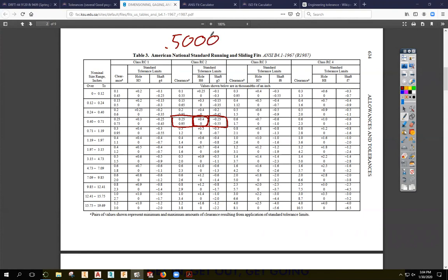So my hole size is 1/2 inch, right? My tolerance is going to be plus 0.0004 minus 0. That's 0.4 thousandths. So thousandths is there, 0.4 moves it one more place. So an RC2 fit for a 1/2 inch hole, it has that much space. Okay. The shaft that's going to go into that has that tolerance. Okay, see, negative, negative. Should be 1/2 inch, negative, negative.